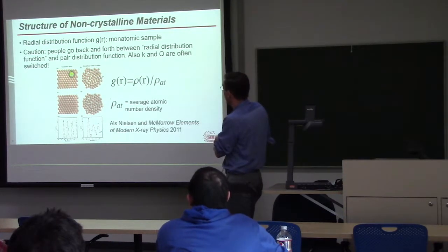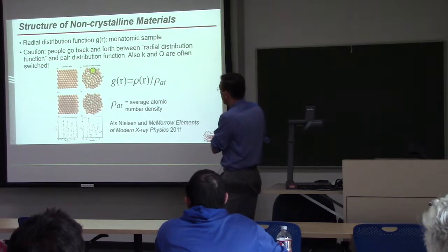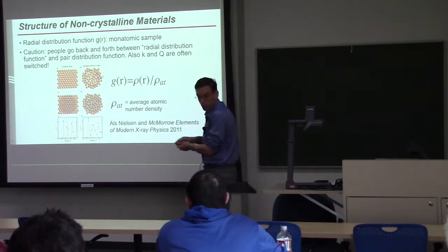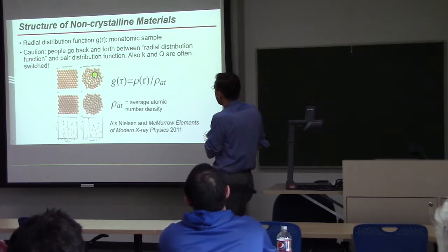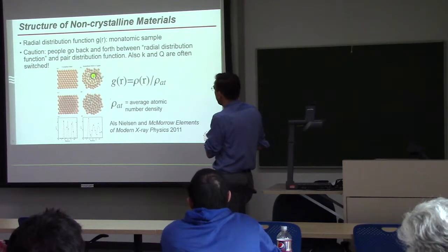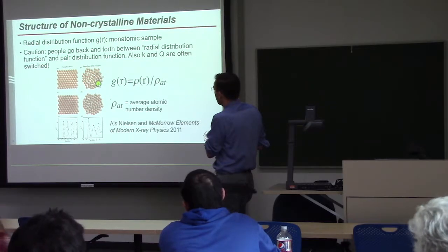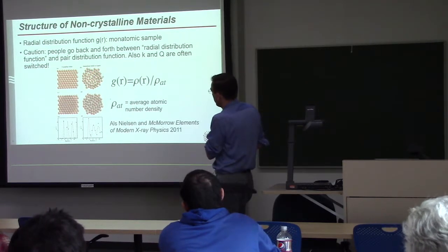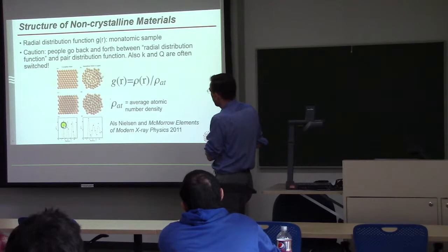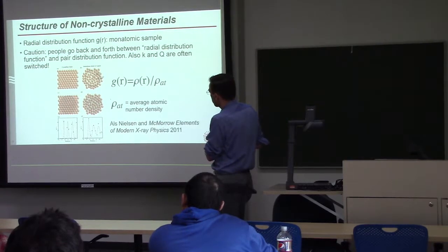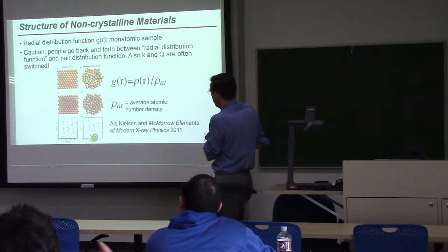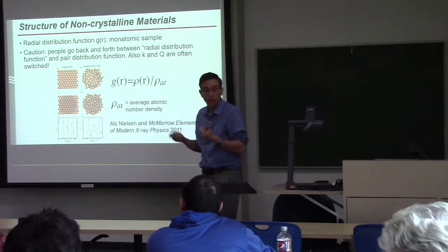materials. There's a crystalline solid on the left and an amorphous solid, or a liquid, an instantaneously frozen liquid, on the right. And you can see that if we integrate the number of atoms that appear at a distance r within a stripe dr wide, you'll see that at the first nearest neighbor's distance, these solids are very similar. They have similar numbers of nearest neighbors at a similar distance. That's because the local packing is satisfied.